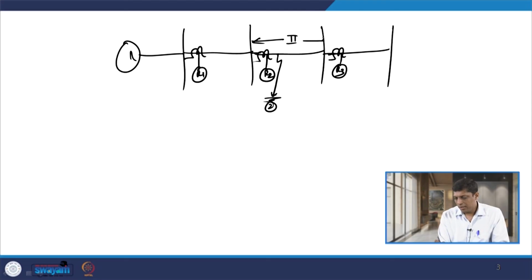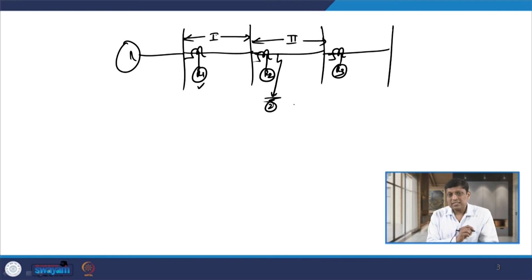It may be possible that relay R1, located in line section 1, operates. This is against the selectivity criteria of protection, because the fault is in section 2. Relay R2 has to operate instantaneously as the primary relay and R1 should not operate. But if, by mistake, relay R1 operates for this fault, then this phenomenon is known as transient overreach.